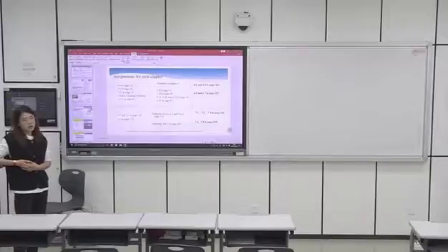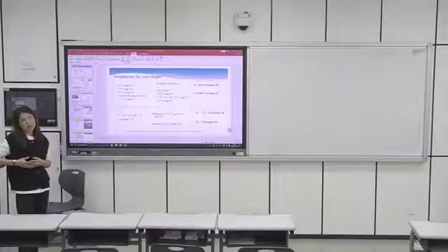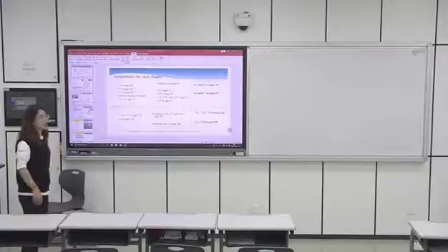So if it is well-graded or poorly graded. And we know that there is a range for CC and CU. If CC is within 1 to 3 and CU is higher than 6, then the soil is well-graded. If not, it is poorly graded, right? This is the main thing in chapter 2.